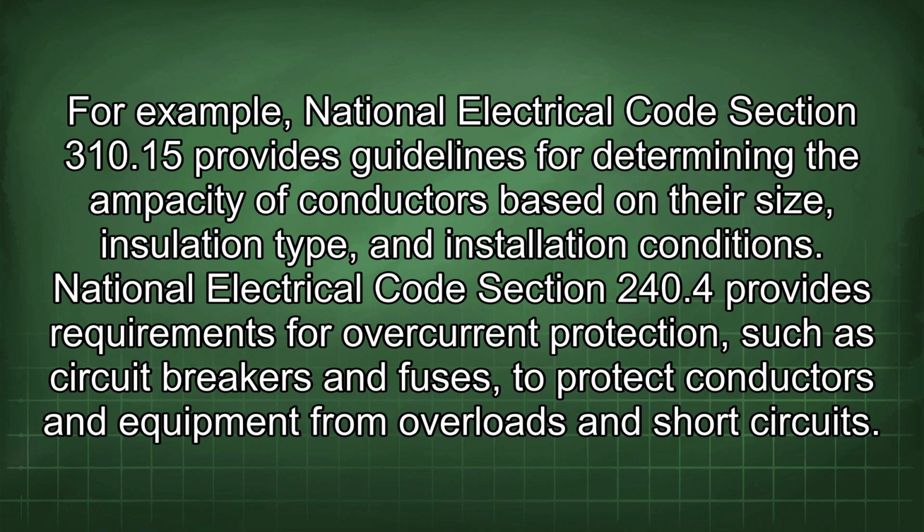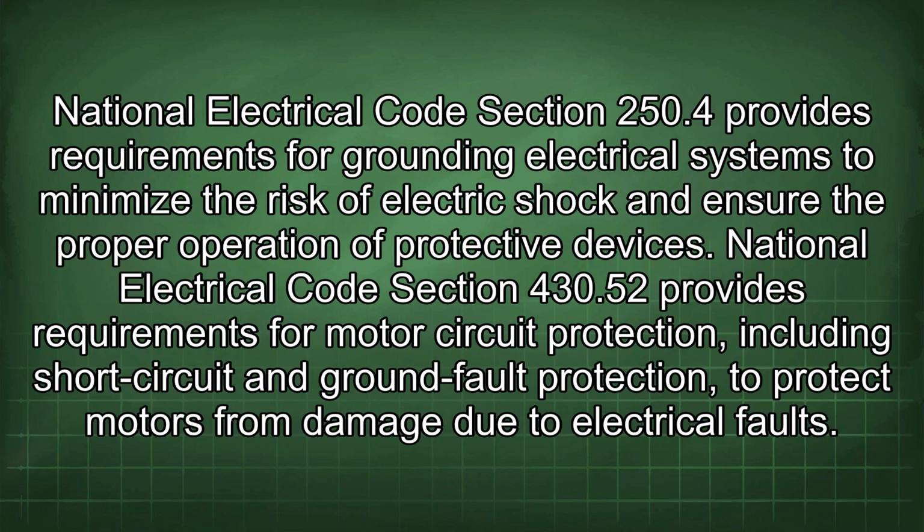conductors and equipment from overloads and short circuits. National Electrical Code Section 250.4 provides requirements for grounding electrical systems to minimize the risk of electric shock and ensure the proper operation of protective devices.